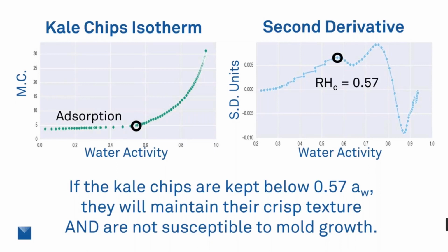But if you have a vapor sorption analyzer, like I mentioned earlier, you can just take your sample, and after 5 minutes of prep, you place that in the VSA chamber, and you can walk away. After about 48 hours or slightly longer, you'll have that complete isotherm for your product. Yeah, and this is actually a service that we offer here. We do have lab services. We have VSAs, obviously, to sell, but if you're interested in just testing this out, you are able to send a sample in and have us test it for you and give you the results for your product.